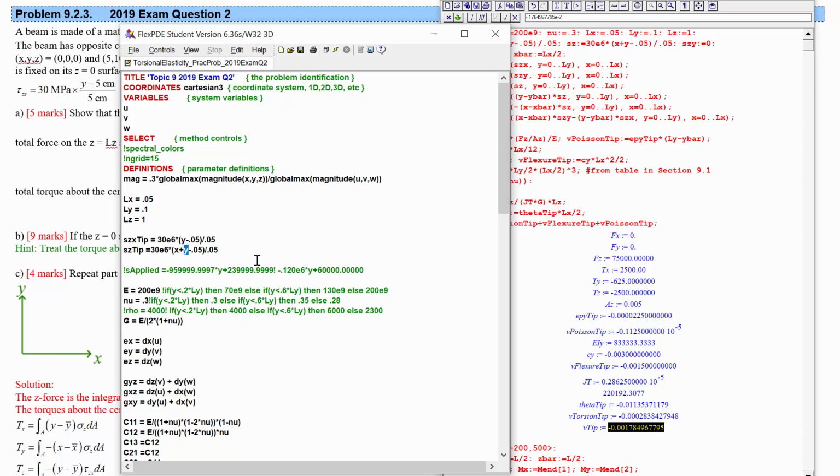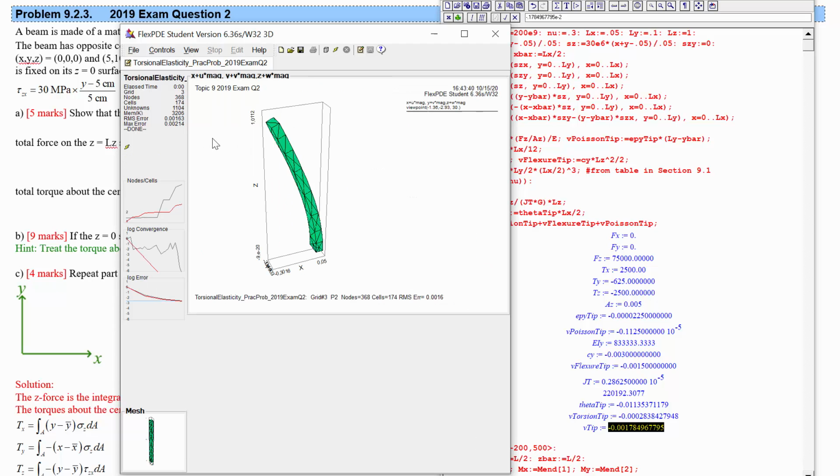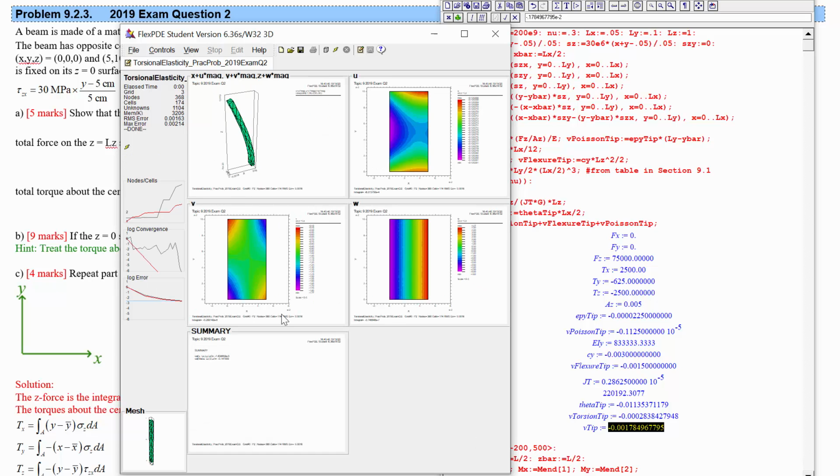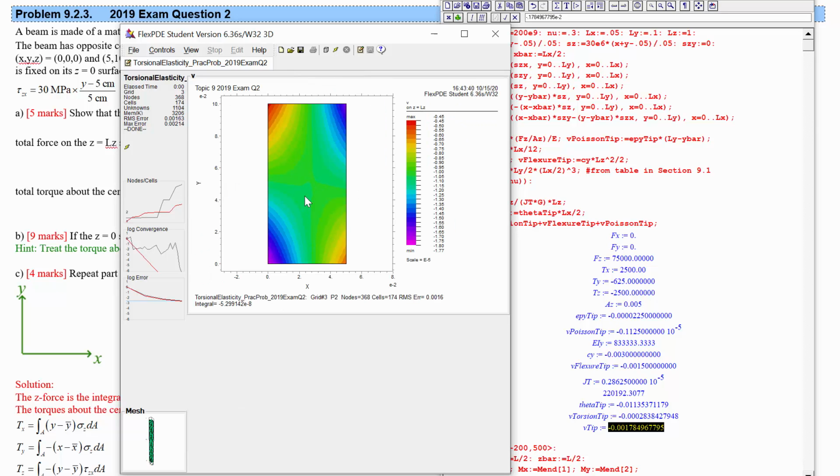for bending in y. Just for fun, let's get rid of the torsional moment, and let's get rid of the y dependence on the stress at the tip, the z stress, which should be getting rid of the moment that causes the thing that causes a moment about x and the thing that makes it bend in y. Now we should have almost no displacement in the vertical direction. Very little going on there.